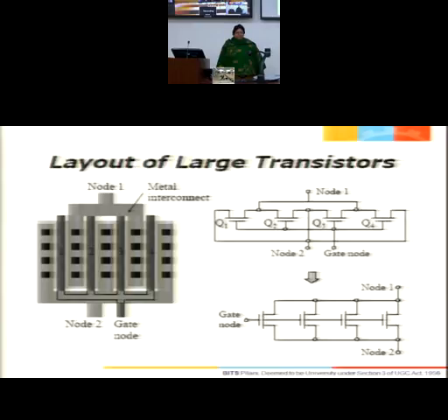Actually, I want to create one transistor, but I would be getting a single one implemented by using 4 small unit transistors, I will say. Unit does not mean W by L is unity. No. Unit means a block, a unit block, a standard unit that I have chosen for myself. It may not be the standard unit for you. It's for me. I have chosen a certain standard unit for myself, and then I'm keeping it the same. I'm not changing it in that layout.